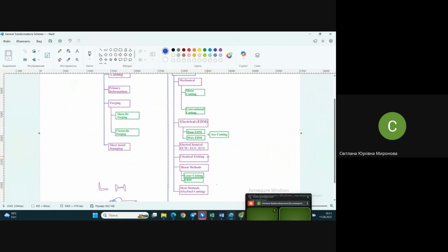Some techniques, once again, do imagine that we are trying to cut a piece of glass mechanically. More probably it will be broken. In case of using a special grinder, not completely cutting it, but just scratching it, next we break it, with unreliable results. But we have other techniques to cut it. In particular, heat methods may be used, laser cutting may be used, and so on.